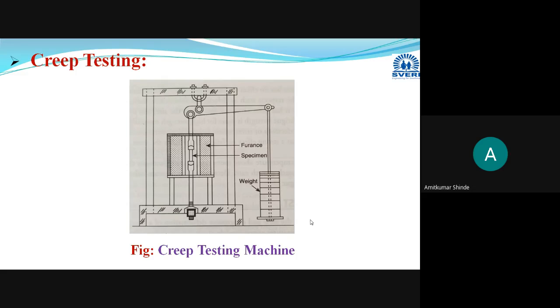That will be our temperature value for conducting this creep test. Are you getting this? The stress values also will vary, and sometimes we check with different temperatures also, but generally the temperature taken in the test condition is 0.4 times the melting point of that particular metal under test. Okay, and this is the meaning of creep.